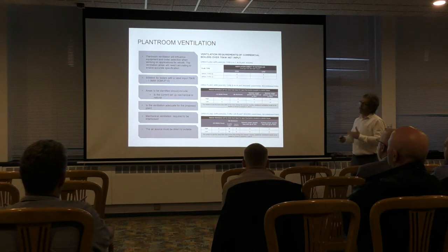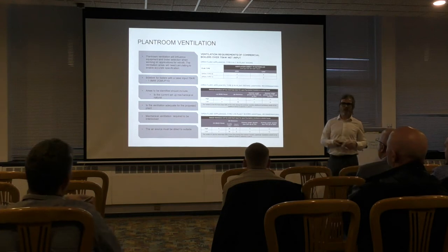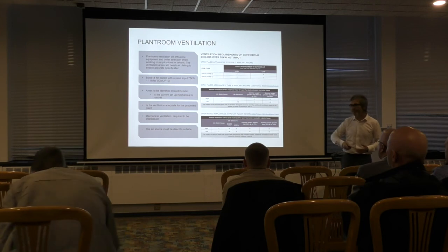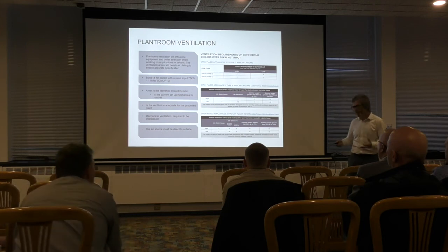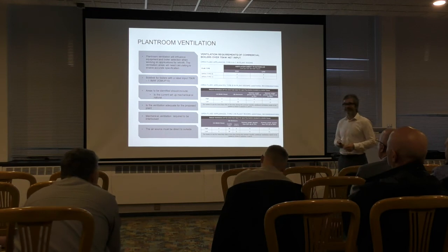What we need to identify, in our existing plant room, is what our setup is at the moment. What have we got? What is our ventilation? One thing I would mention is that if you go into a plant room on a day that's not very warm outside, in the winter, and the boilers are firing but the plant room's really hot, you think, it's a bit warm in here. Straight away, that's a key indicator that ventilation isn't up to scratch in that plant room.